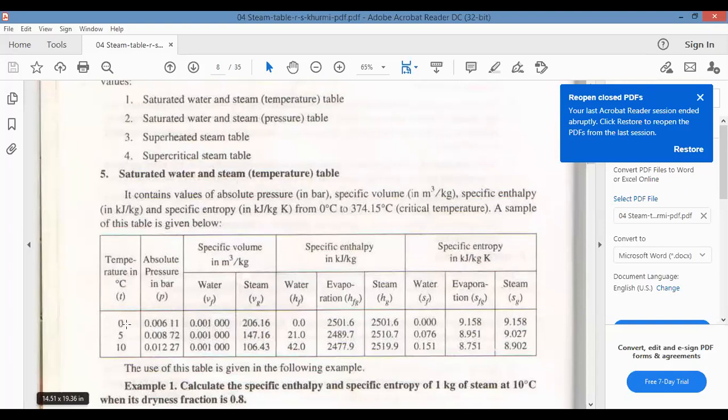If you want the water to boil at 0 degrees centigrade, now you know that it would actually freeze, but let us say the water has to boil at 5 degrees centigrade, the pressure is 0.00872 bar. That has to be the pressure which has to be maintained.